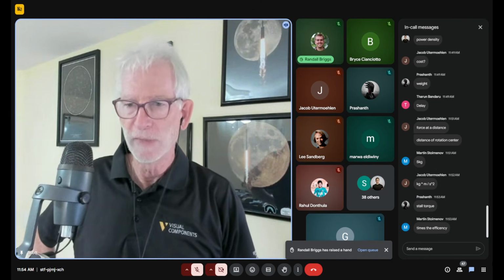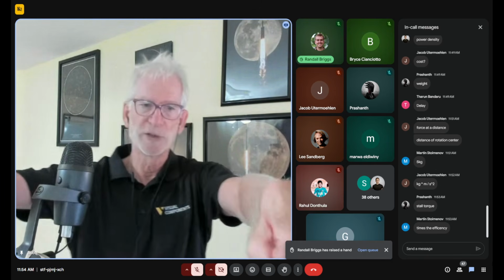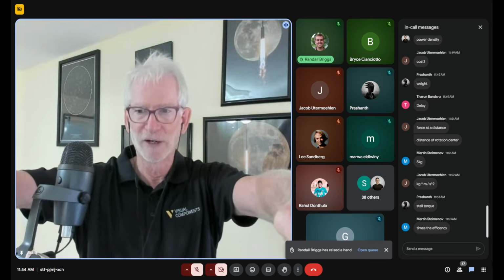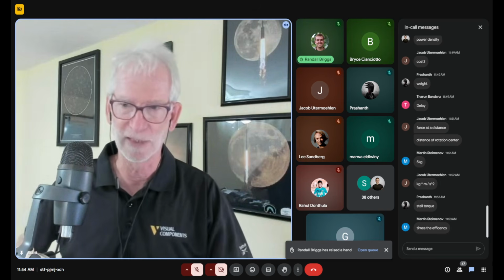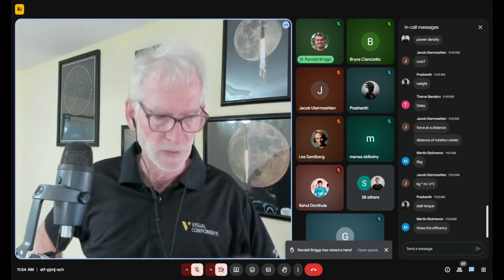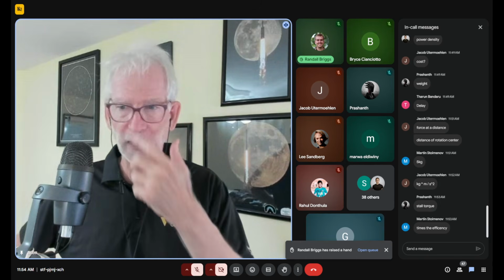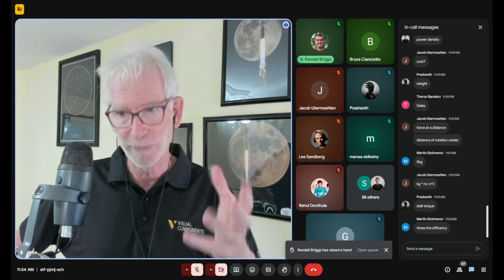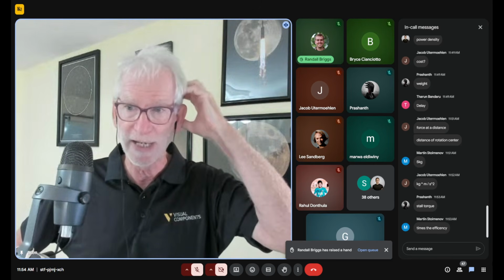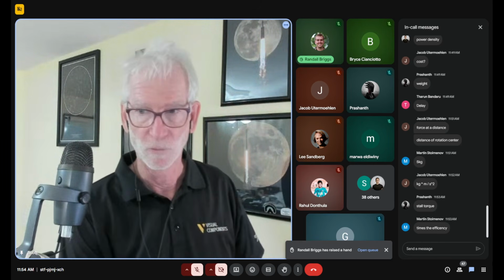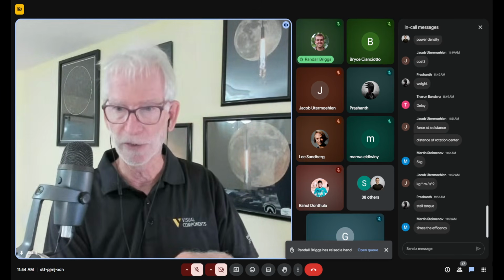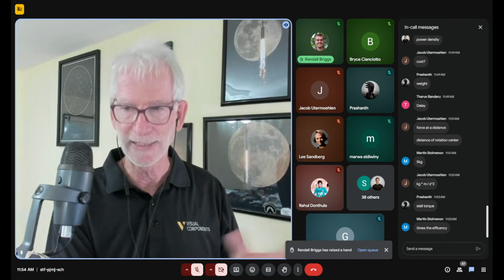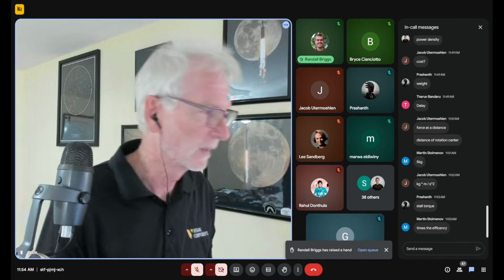If you don't believe me, all of you get up and hold your arms out and see how long you can hold your arms out without any payload. You're going to realize, oh yeah, it gets pretty heavy pretty quickly. So when you're coming up with these torques, you've got to look at a variety of situations to decide what I'm going to need and what is going to be sufficient. And we will get into stall torque as well towards the end. That is something else, which is also an issue.